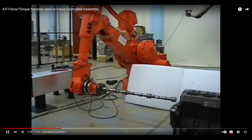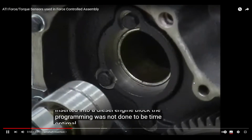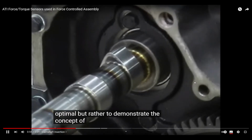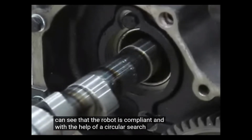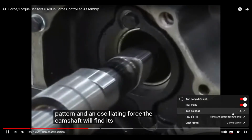Camshaft. This part of the video shows a camshaft inserted into a diesel engine block. The programming was not done to be time optimal, but rather to demonstrate the concept of force-controlled assembly. You can see that the robot is compliant, and with the help of a circular search pattern and an oscillating force, the camshaft will find its way in.